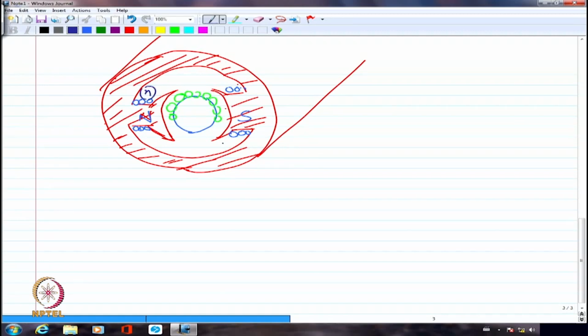This will also have certain number of turns N here, and some current I is going to flow through this. Some same current I is probably going to flow through this as well. So, I will have in all probability 2Ni as the MMF in this case. I am showing two poles, each of them consisting of N number of turns, and both of them carrying a common current I, if I connect them in series. So, this is going to be the MMF.